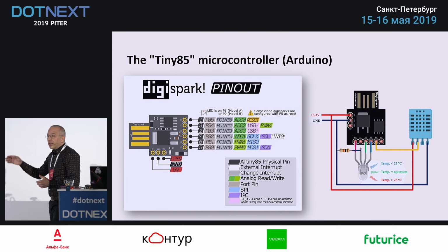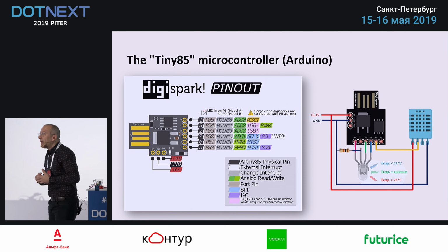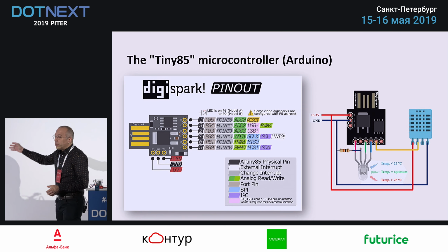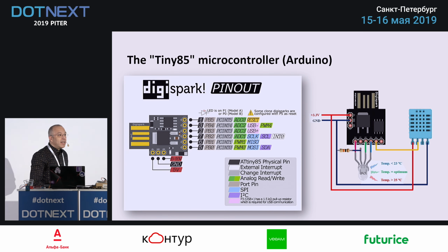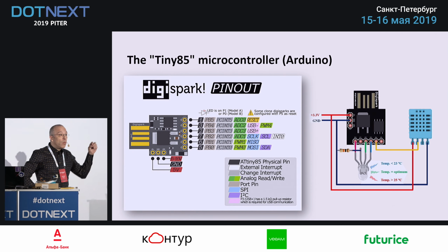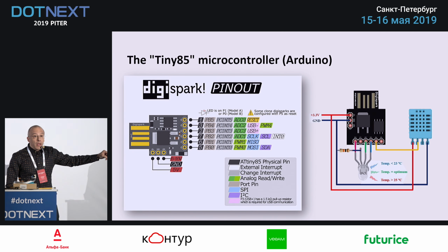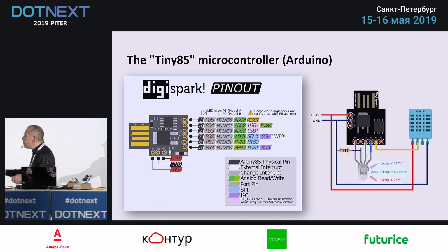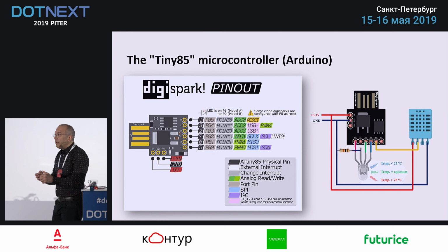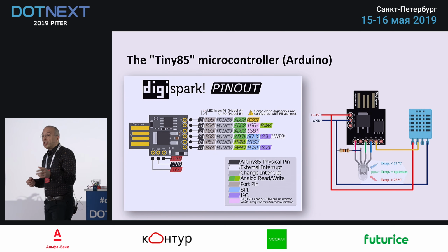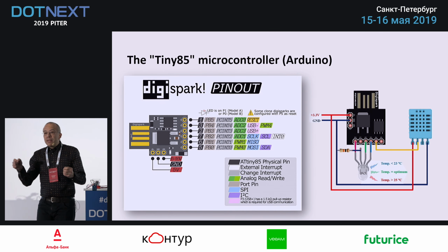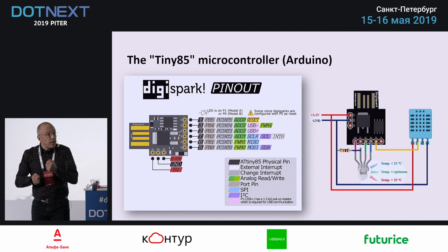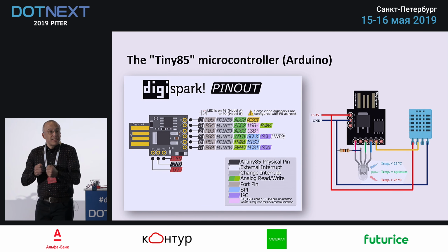And you have IOs at your fingertips, so you can use whatever you want to interface with other devices. And the blue device that you can see here is a temperature device, which is a digital device. It's a one-wire communication channel, which is tricky. Even if it's a very small device, it can give you temperature and humidity, DHT11 or 22. This is extremely tricky because one wire means being extremely precise in the clock. So the communication must be extremely precise.